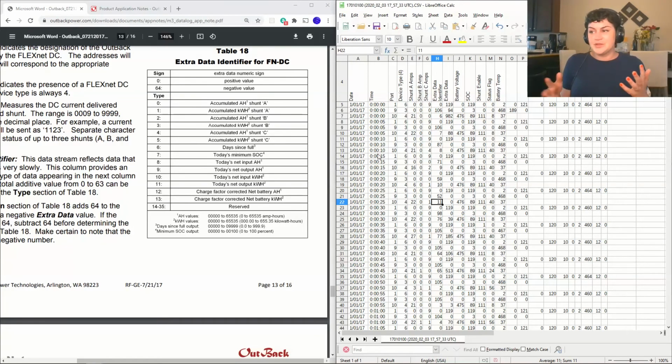Or it could be high temperature. Your unit is getting too hot, so it has to shut down in order to cool down. You can get temperature data and stuff like that. This data logging is really useful, especially because you're getting it from the device's perspective. It's giving you exactly what the device thinks it should be doing and what it's reading at the time. Voltage, capacity, temperature, error codes, warnings: these are the places I usually look when troubleshooting. There's also a configuration file that you can get.